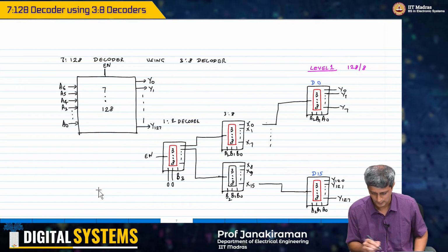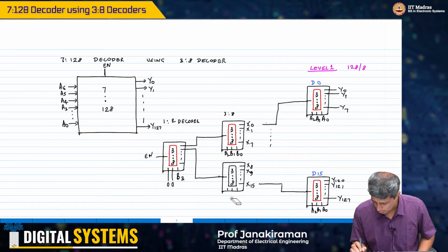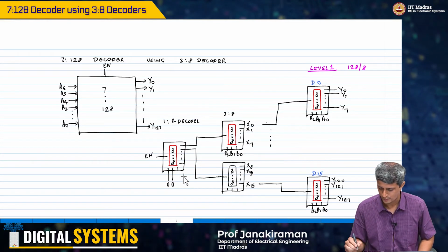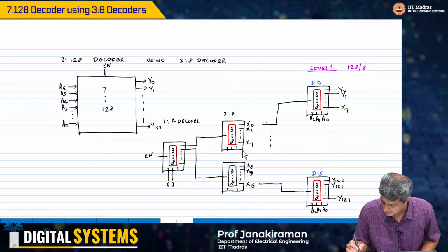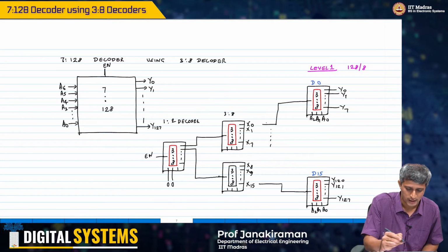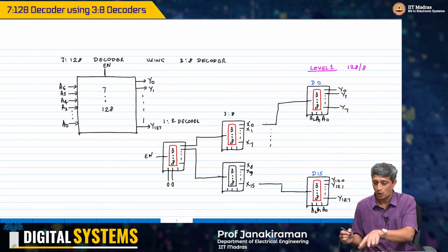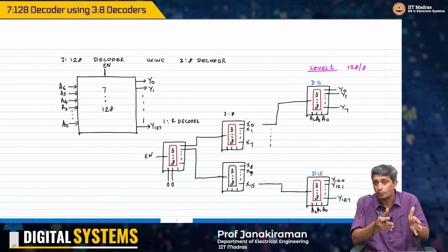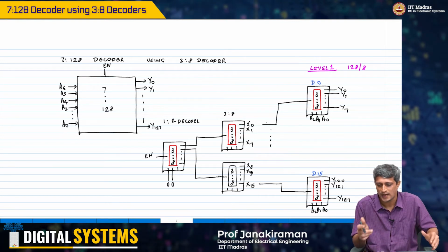Okay, I have this nicely done, and all I have to do now is connect these, these are my lower order bits, and therefore what I need to do now is this 3:8 decoder on the previous stage, which is basically the 4:16 decoder that we have built, right.